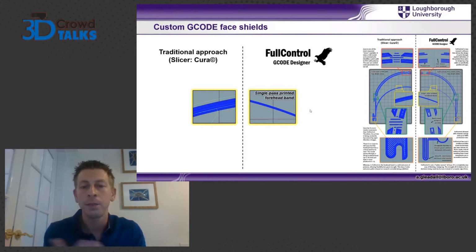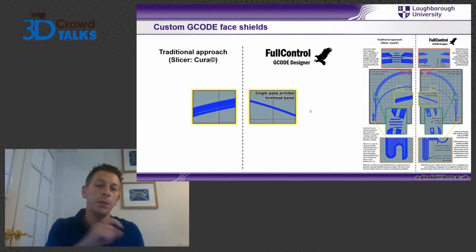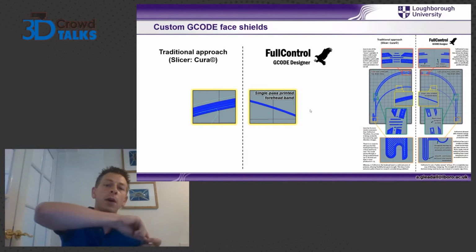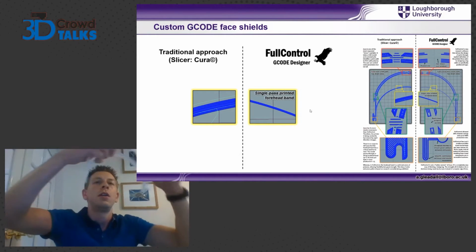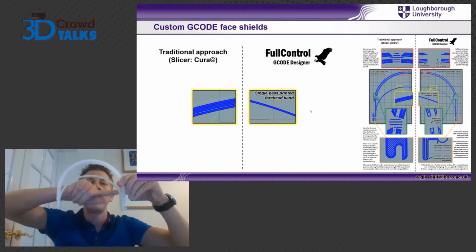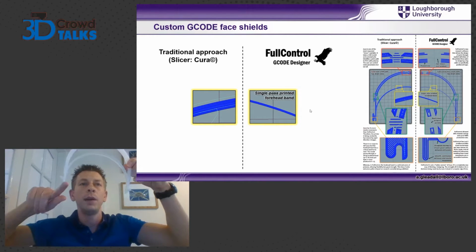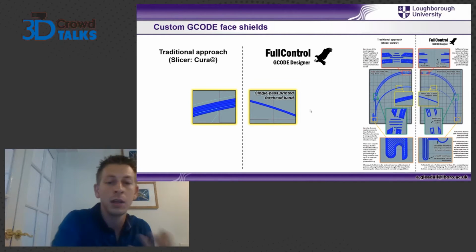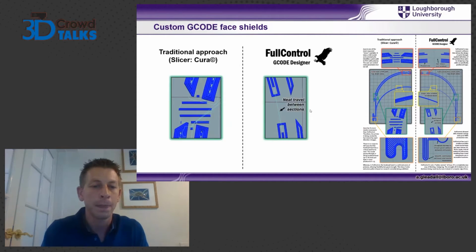With this, when I designed the toolpath, I simply said, right, we can do a 1 millimeter headband with a single filament pass. So that's what it was. So there was no point did the nozzle ever leave that headband or have a seam where it started and ended, because it printed all the way from the very bottom left of the visor all the way along that headband to the very far bit, and then carried on smoothly around the corner. So there was no seams, and that really improved post-processing time.